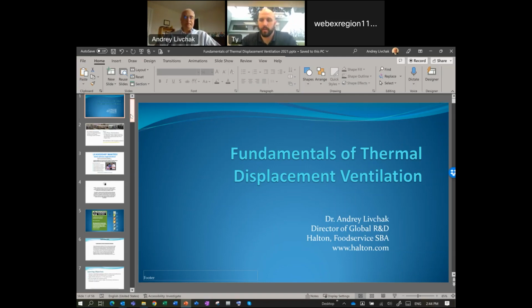Awesome. I thought that was extremely interesting, increasing the efficiency of some of that. Yeah, the efficiency would be better compared to all-air supply, because when you supply warm air through ceiling diffusers, this air stays in the upper part of the space and doesn't circulate back. Yeah, right. That makes a ton of sense.